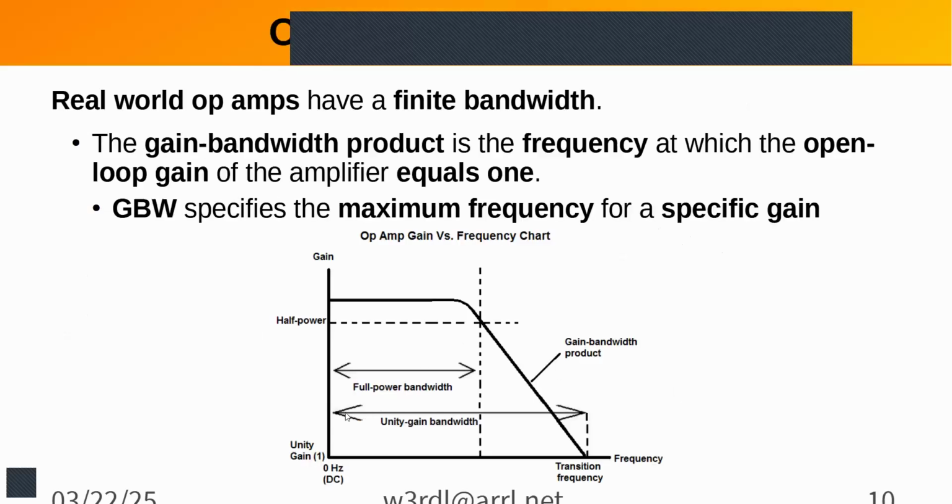All right, I'm down here at a gain of 5. Say that's what that line is. As I go along this line, I'm changing frequency. The gain hasn't changed. I don't have a problem till I get up to the line and then I start losing gain. So at that point, the gain changes with frequency, but not in the operating range.